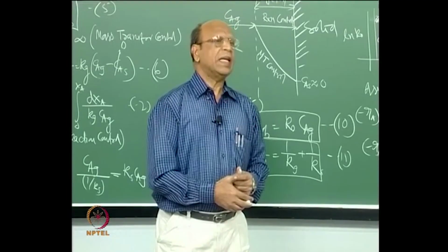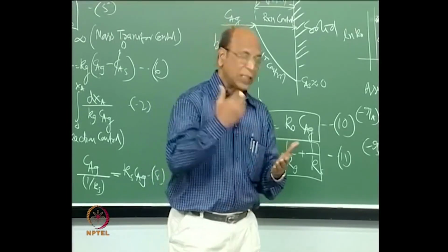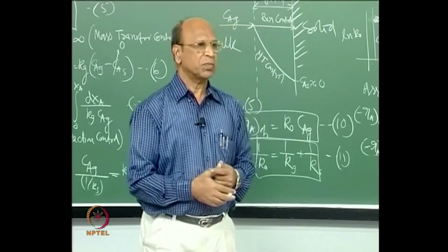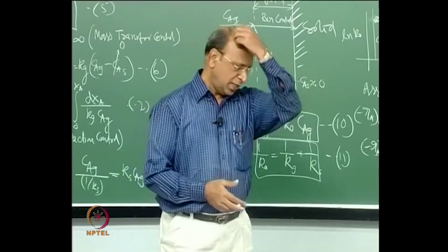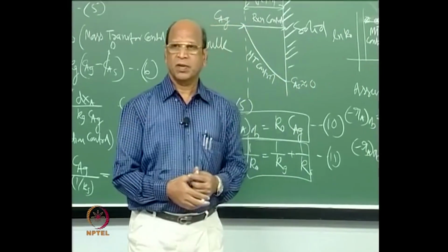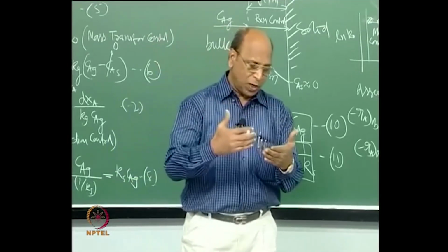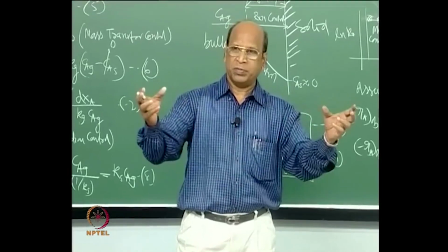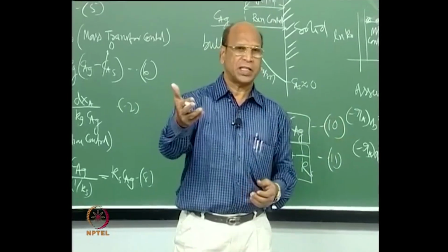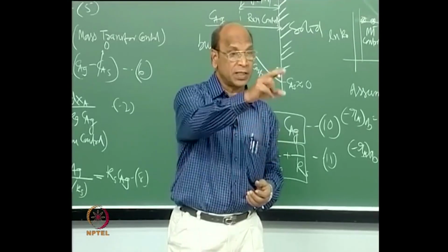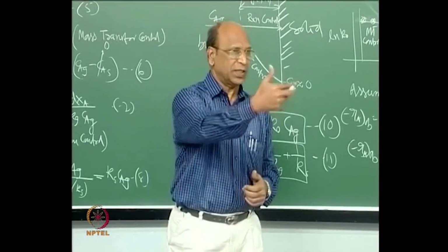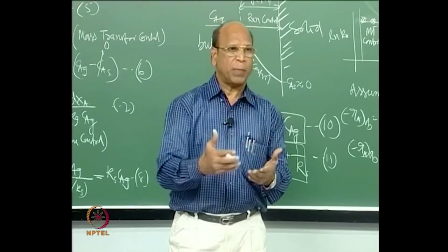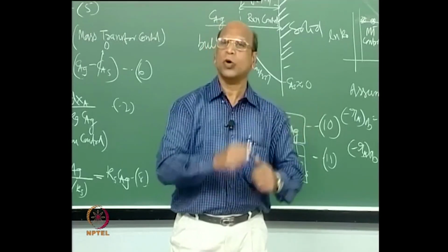Reaction is very fast. Yes, gas phase reactions have very small residence times, in fact only in the form of seconds. And when I have residence time in seconds, it is very easy for me to provide that residence time in plug flow. Plug flow, we know, is definitely more efficient than mixed flow because of the residence time distributions. That is why all of us would happily go for plug flow, but still many times we do not.